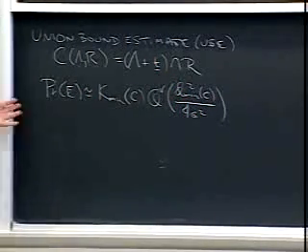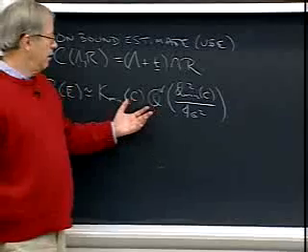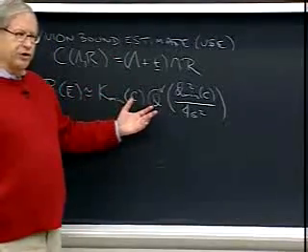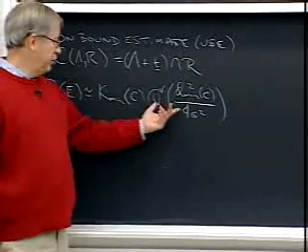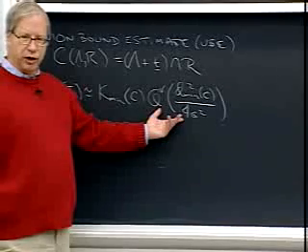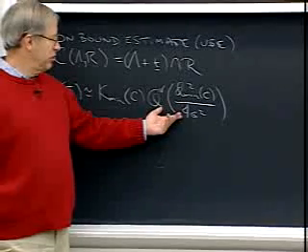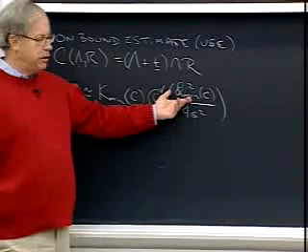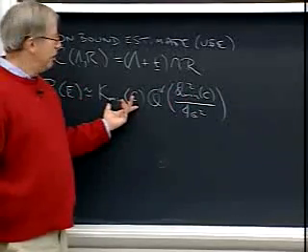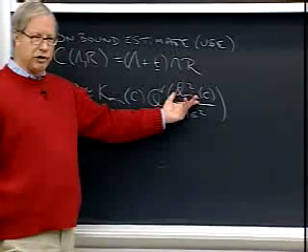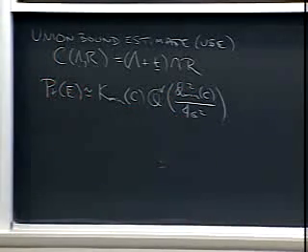And you remember how we got this. We took the union bound, we took all the pairwise error probabilities, and from that we get K_D contributions at every distance D. We added them all up in the union bound. We said, well, for moderate complexity and performance, at least this is going to be dominated by the minimum distance. So this is the minimum distance term. This is the number of minimum distance terms, and this is the pairwise error probability we get for each minimum distance term. Okay.